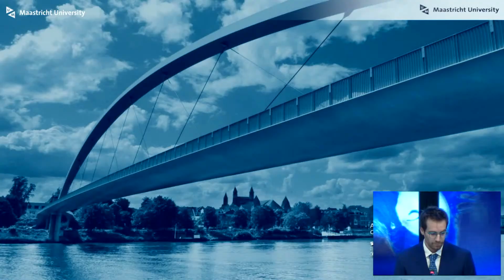You made it very fluid dynamics based, but as you mentioned yourself, quite often temperature plays a very big role when processing these materials because they have a very big effect on viscosity. Could you elaborate for me how you incorporated temperature? Do you assume one constant temperature in the polymer always? How realistic is that? What are your heat sources for temperature, and how do you accommodate the different types of materials which are in your print head?